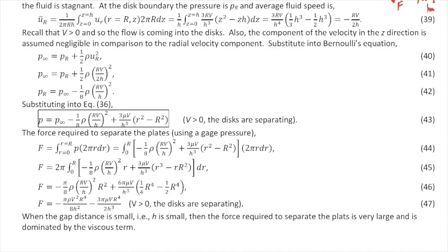So that's why when we had our two mirrors against one another, and I pressed them together, and gravity's acting downward, this bottom plate didn't immediately fall. It took a little time for it to fall. It actually stuck onto the surface, and it's not because of surface tension or electrostatics or anything like that. What's happening is that there's just a flow of air trying to fill into that gap, but the pressure inside that gap was very small. And so you had a net force acting upward on that bottom disc to hold it in place.